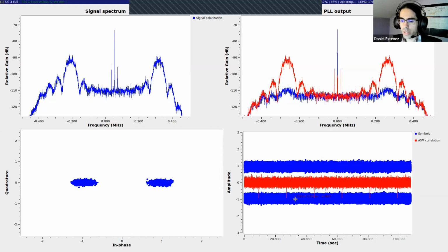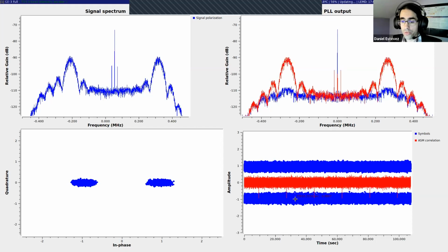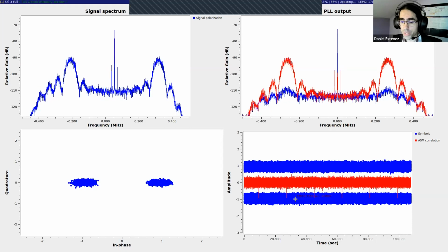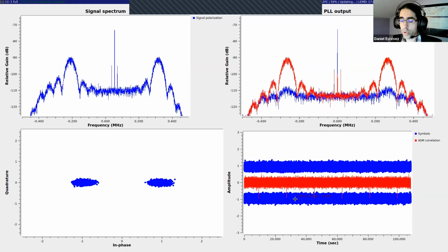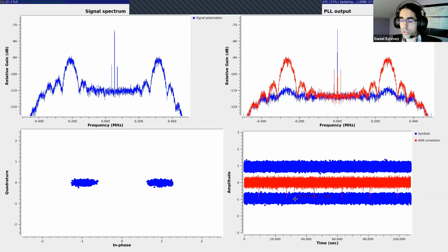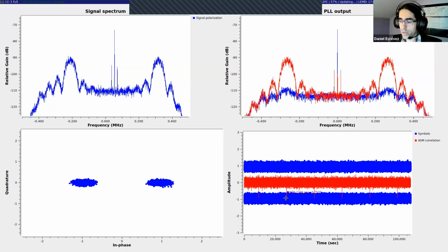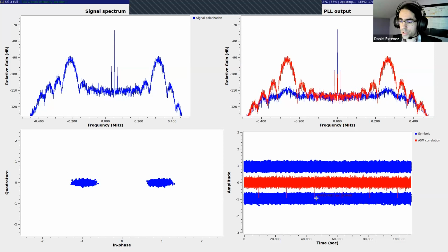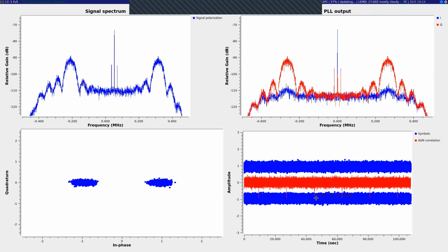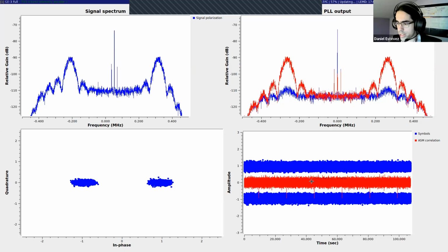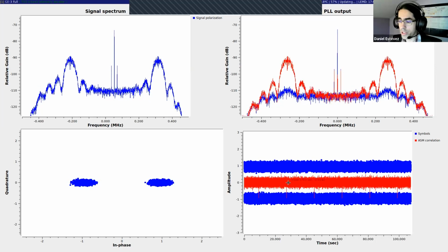We do this by doing some mathematical procedure which is called correlation, and is used to find a particular pattern in a sequence. We can look for that attached synchronization marker and plot the places where it can be found. And that's shown here in the red plot. So you can see these spikes, these correspond to locations of the attached synchronization marker. They are obtained with this correlation. And the stuff which is between each of these two is one of these code words.